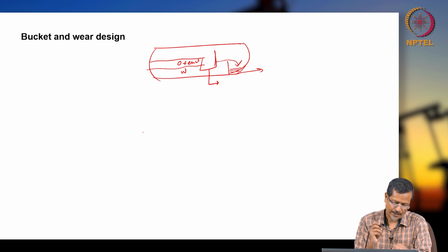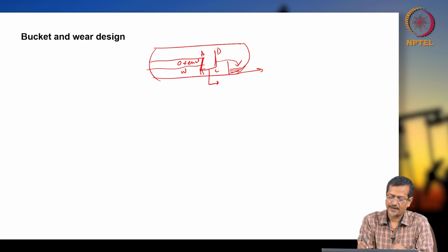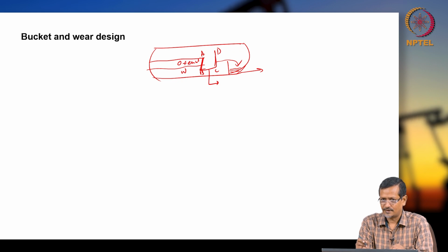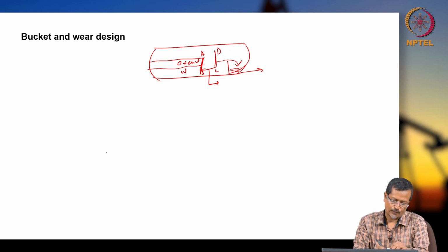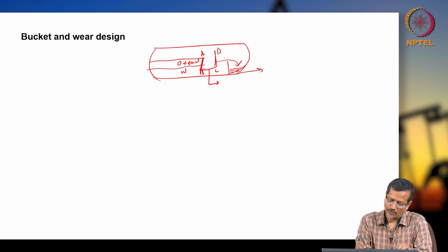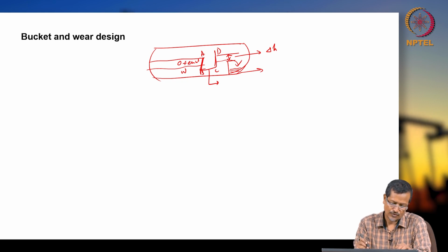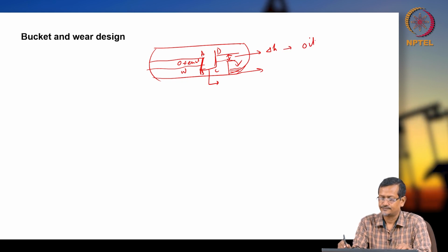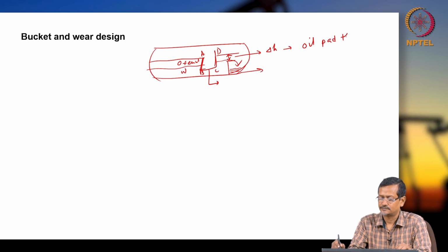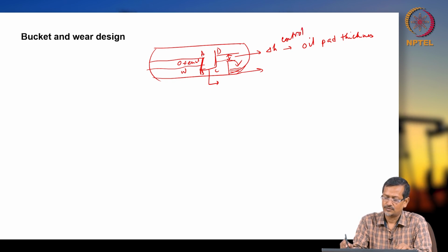Okay, now the height of the water weir controls the liquid level. So this water weir height, like A, B, C, D. So this A, B height will be controlling the liquid level. Okay, the oil and water weir height difference controls the oil pad thickness. So this oil and water level, this height controls the oil pad thickness.